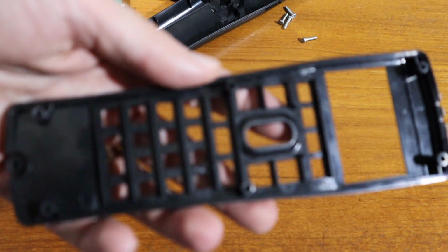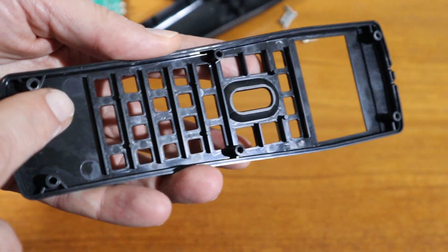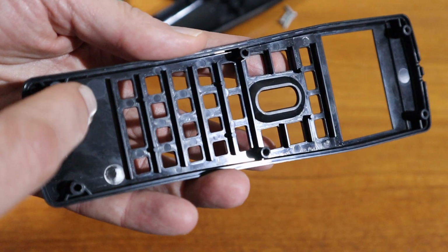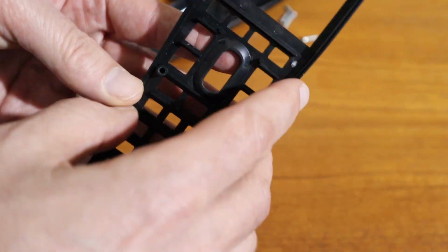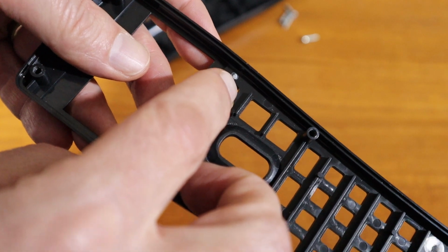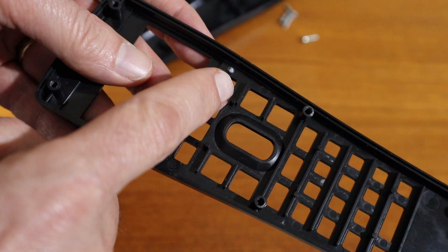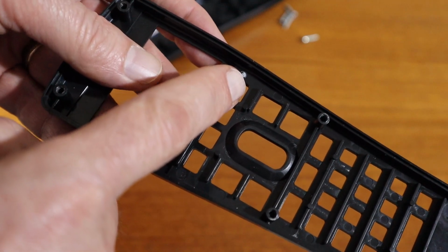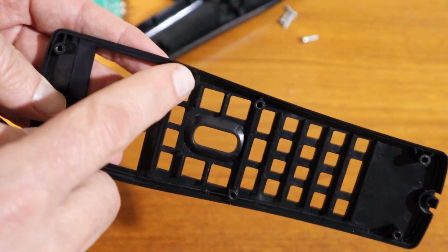Same thing for the top half. We have ejector pins in various locations, which is what produces those marks. That's what pushes this out of the mold. And then looking here, you can see that right here, the plastic is a little bit white. The reason it's a little bit white is because they sheared off the gate right there. That's where the plastic came in, and it filled this entire part from that one location, which I think is pretty impressive.